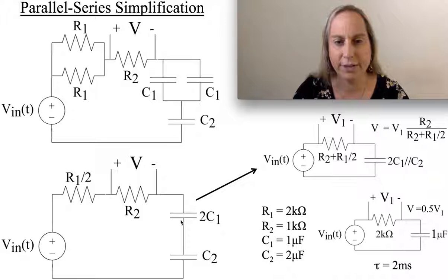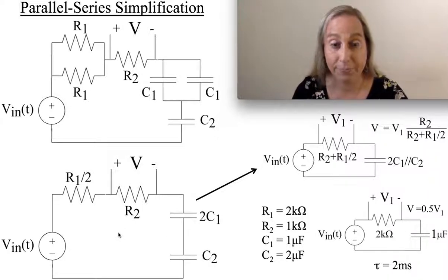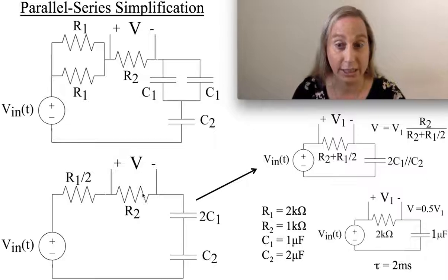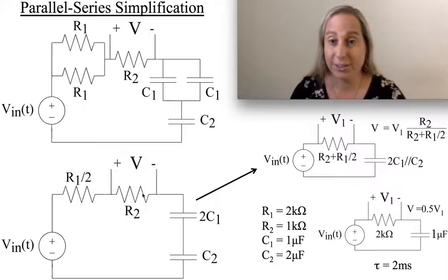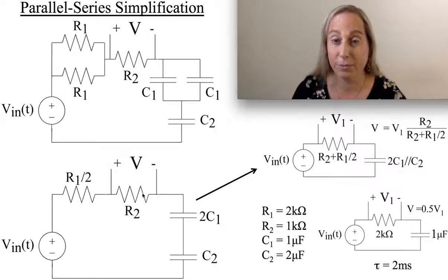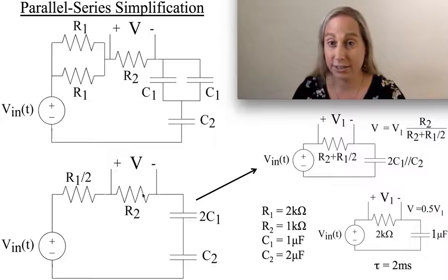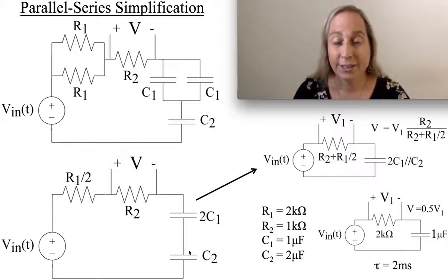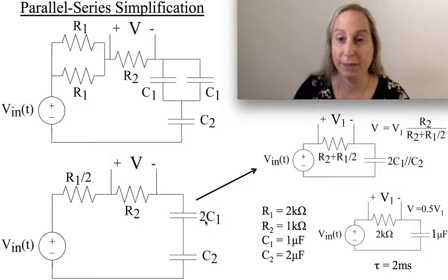And you look at the circuit down here and think, well, that's certainly better, but still a bit to think about. The first thing is I can take the two resistors in series and they add, so I add those values directly. One of the things you start to notice is that there's an interesting dualism between resistance and capacitance. Another way to think about it is a dualism between resistance and conductance. You'll see this as you work through other circuit elements. If you look at capacitors, you get two of them in series, but capacitors in series behave like resistors in parallel.